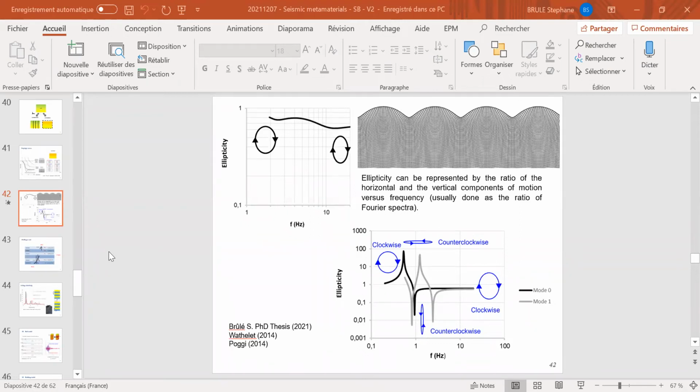Surface geophysics is based on an impact at the surface. This impact is propagating in the soil, and we have receivers. What we can observe is that according to the layering of the soil, you can have a strong dispersion effect, and we're trying to find this soil profile by inversion method. But when we do the exercise coming from a homogeneous medium and transforming it a little bit by adding layers, you can see this.